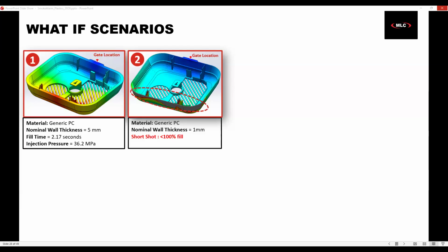And if I were to look at the ease of fill, even though the pressure was not high here, the pressure was spiking over here, there's still something that's detecting that this has a problem in this section. This would require potentially a massive amount of pressure to push the remaining material to fill this section consistently. So we can easily see that and know that between the pressure and this, we need to do some other type of change. So we have two options.